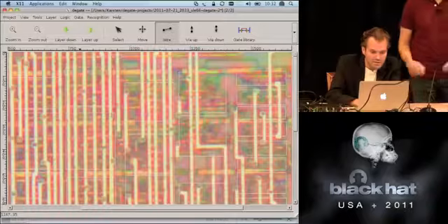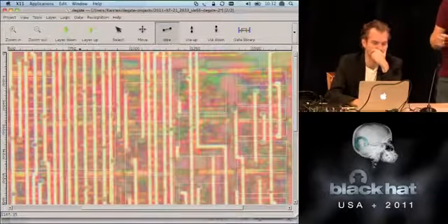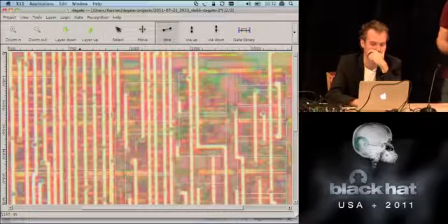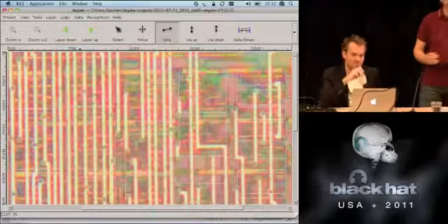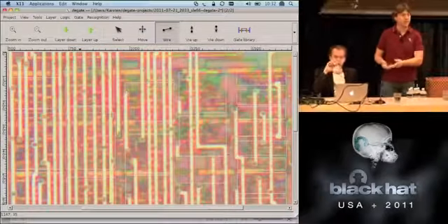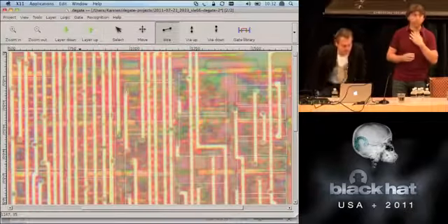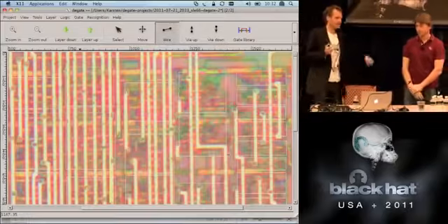Oh, no. This brings up a good point, Carson, what you just brought up. We're not seeing fake tracks anymore on these newer technologies since they've started planarizing, going under the 500 nanometer range. ST used to do this. They'd hide tracks that had dead ends, went nowhere. Right. Useless logic. Carson would have realized this in D-Gate. Using the tool, it would have been like, hey, this is an open end. Well, in fact, we did see dead ends on one chip, so we kind of switched around the logic.